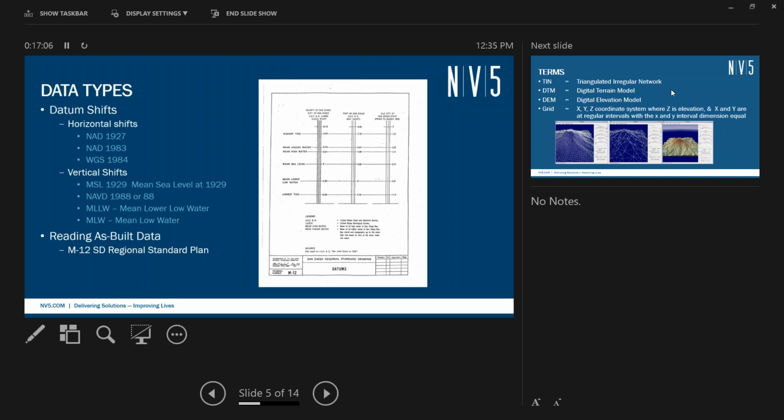No, it's a diurnal cycle that actually goes, here's the high point, so it's a mean higher high and a mean lower low, then it comes back up and is not as high, so it's mean high tide, and then a mean low tide, okay? So there's actually 2 lows in the cycle and 2 highs. So there's a mean higher high tide and a mean high tide, a mean low tide, and a mean lower low.